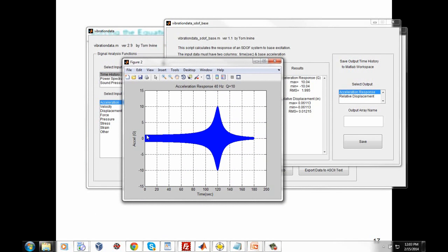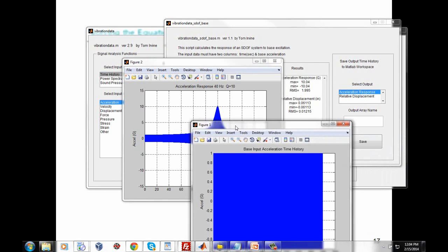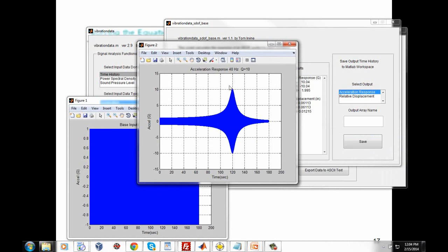Now at the lowest frequencies, the excitation frequency is say 2 octaves or so below the natural frequency of our test article. So in this case, we have very nearly unity gain. The response acceleration is just tracking the base input acceleration. Now as we sweep upward, eventually we approach 40 Hertz excitation frequency, and we get this quasi-steady resonant response behavior because we're matching up or coinciding with our natural frequency.